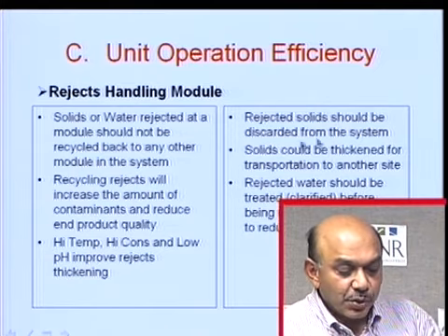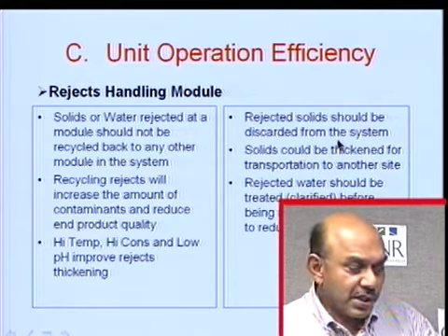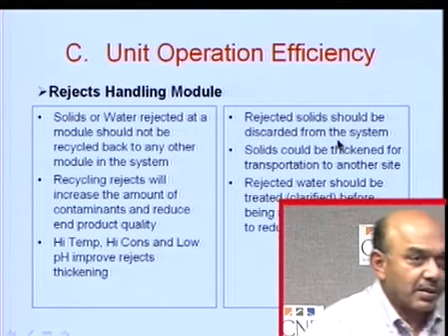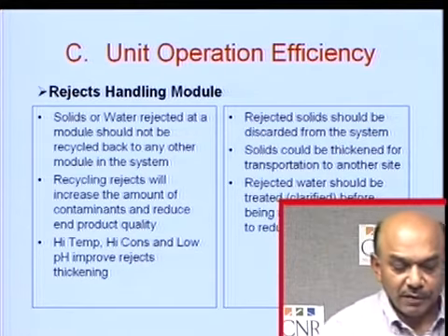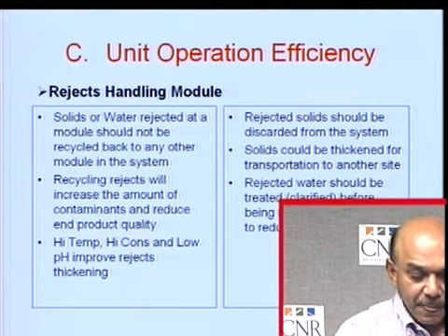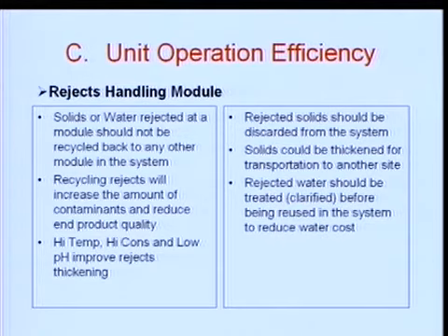Reject solids should be discarded from the system. Do not recycle them. If you can possibly handle them and discard them, it's better off. You've got to do that. Solids could be thickened for transportation to another site so that you can decrease the cost of transportation and landfilling.